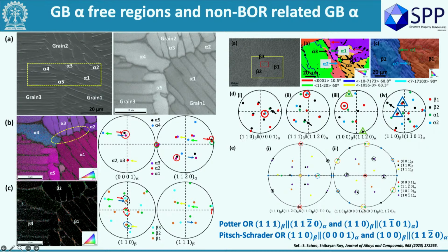If you take a titanium alloy microstructure, you will possibly see 20 to 30% regions that don't have grain boundary alpha. It just appears as if lamellar alpha is coming out on its own on the two different sides. Right? That's what we saw here, this kind of regions. It is coming out on its own without any grain boundary alpha. The microstructure is so complex. For them, of course, there has to be some other kind of mechanism that we follow.